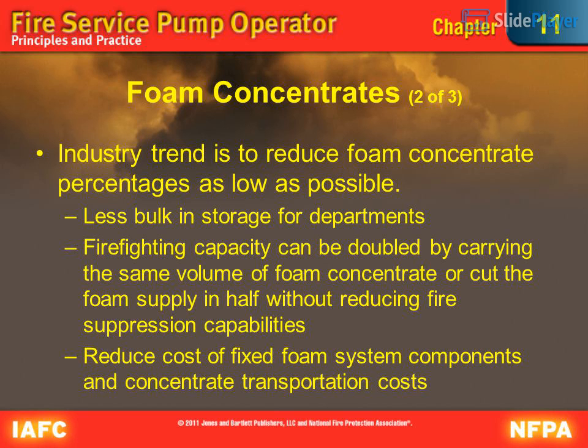Foam concentrates, 2 of 3. Industry trend is to reduce foam concentrate percentages as low as possible. Less bulk in storage for departments. Firefighting capacity can be doubled by carrying the same volume of foam concentrate or cut the foam supply in half without reducing fire suppression capabilities. Reduce cost of fixed foam system components and concentrate transportation costs.